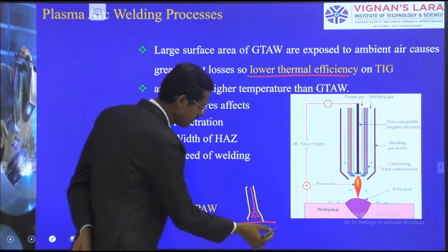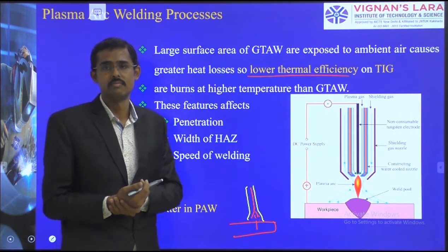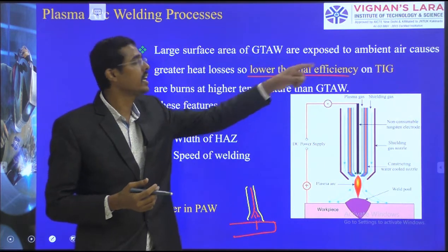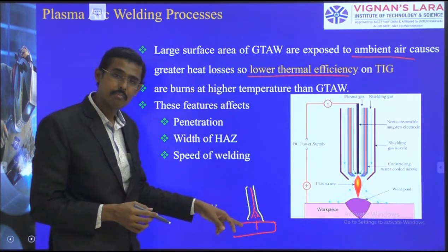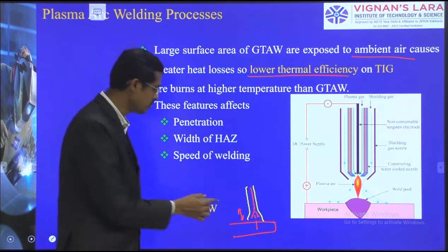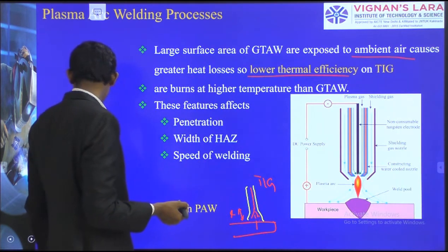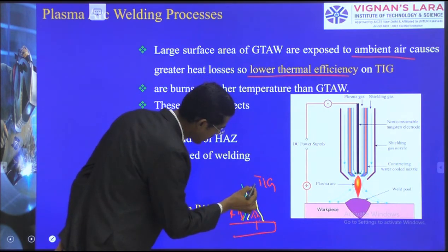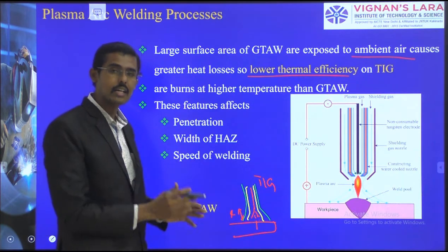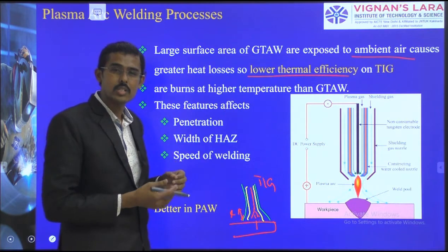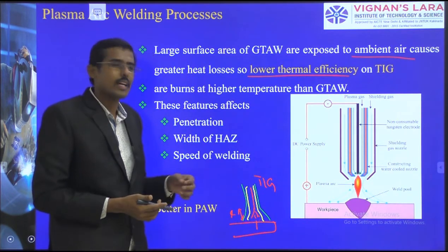But with this single layer of shielding gas protection, ionization is not perfectly made. Ionization is disturbed by ambient air conditions and fluctuations. Therefore, the thermal conductivity across this air gap is disturbed in the TIG welding process. So here I am trying to give double the protection, in such a way that the plasma ionization takes place at the inner layer, and the ambient air fluctuations and atmospheric contamination are avoided, which is taken care of by the second protection. That is what I am doing in this setup.